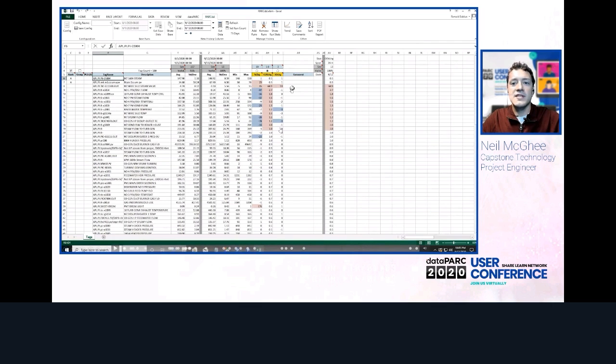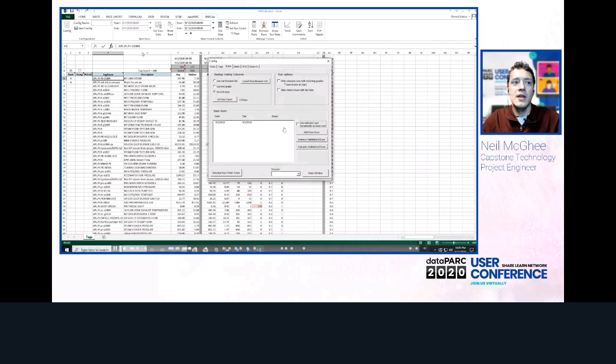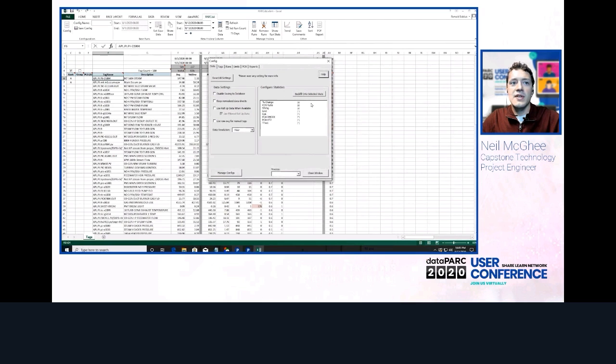These are the standard statistics that we have set up, but there are also some additional ones that we can enable from the configuration menu as well. If we want to know which tag had the largest deviation from its limits, then we can use the limit statistic, which looks at the maximum and minimum values for the comparison period. Limits can be manually entered in the tag configuration columns, or they can be imported from PARCview in the Limits tab. If we want to know which tag had the greatest variability relative to its specification limits, then we can use the CPK.